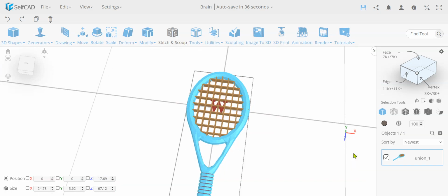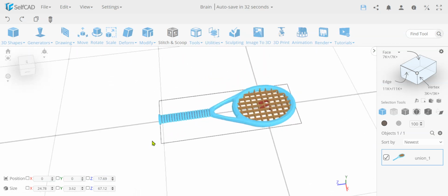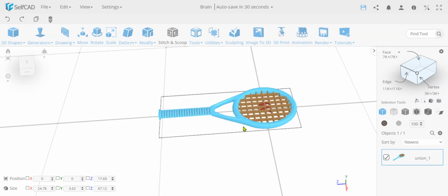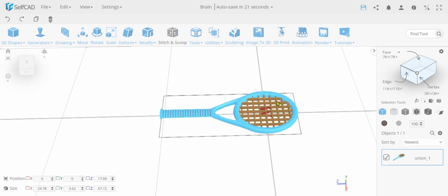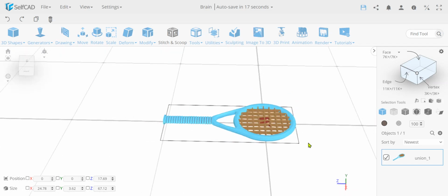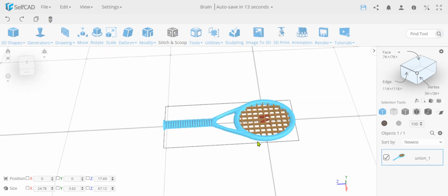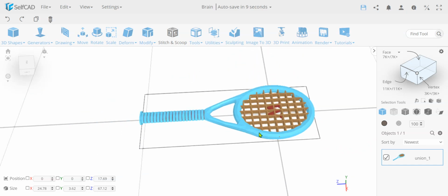So you see we're done with the tutorial, we designed the entire thing. What you learned over here is basically we took a basic cylinder, we gathered the outside, copied the outside faces. Actually you could just copy the faces, but in my case, instead of copying the faces, I just selected the top and bottom, deleted them, so we were left with just the outside faces. I added thickness to make this into something thick, but in that case it wasn't rounded. Later we used a round object to make them rounded.